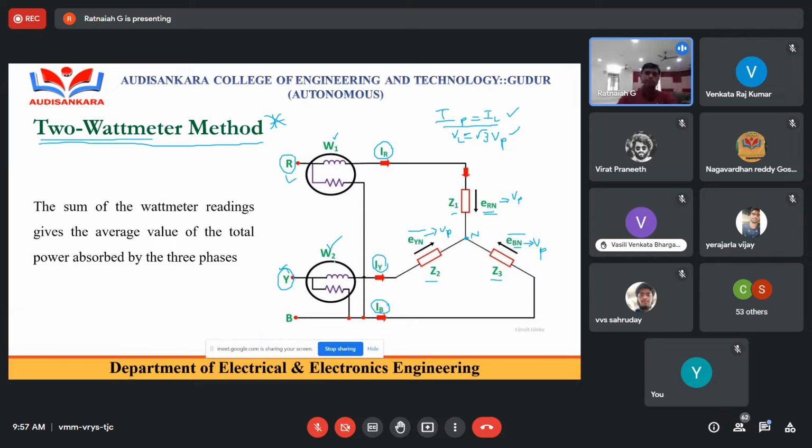Whatever the wattmeters, suppose you connect W1 for the R phase and W2 for the Y phase. The current coil is always connected in series with the load. The voltage coil is always connected to the B phase.